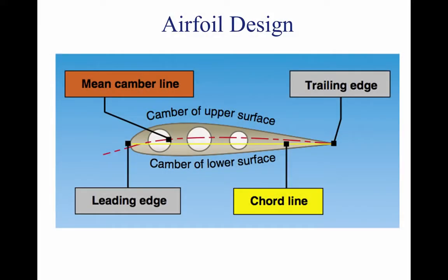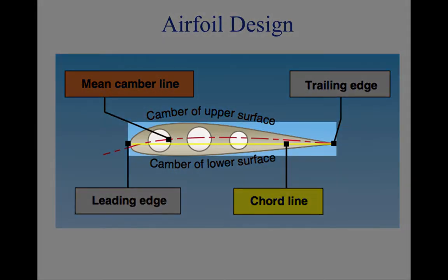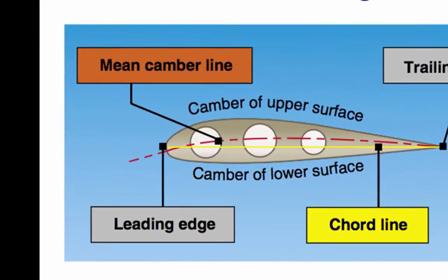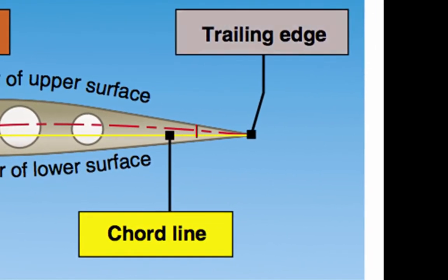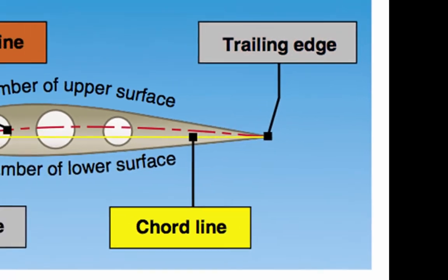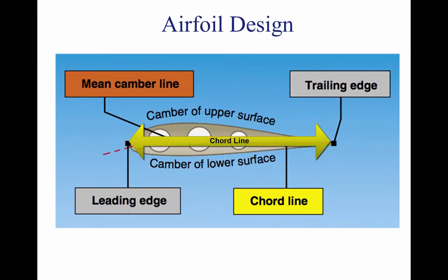An airfoil is a structure designed to obtain reaction upon its surface from the air through which it moves. By looking at a typical airfoil profile, such as the cross-section of a wing, one can see several obvious characteristics of design. The end, which faces forward in flight, is called the leading edge and is rounded. The other end, the trailing edge, is quite narrow and tapered. The chord line is a line drawn from the very front of the leading edge to the trailing edge of the wing. The chord line cuts the wing in two parts, an upper and lower half of the wing.